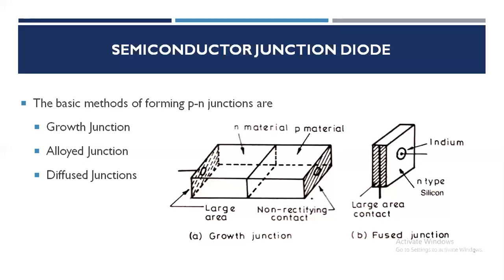The substrate crystal may be a wafer of the same material as the grown layer or a different material with a similar lattice structure. In this process, the substrate serves as the seed crystal onto which new crystalline material grows. The growing crystal layer maintains the crystal structure and the orientation of the substrate.